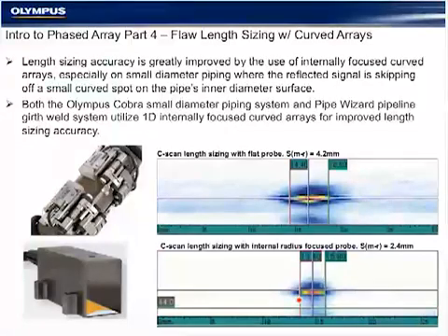in some of our small diameter pipes, even a 1 millimeter hole in the pipe will look distorted on the B scan and C scan and measure 2, 3, or 4 millimeters depending on the frequency of the probe. For that reason, it's important that our length sizing be accurate.